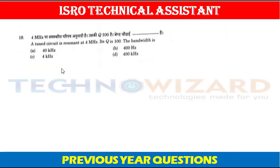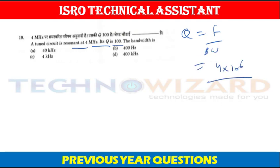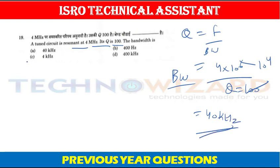Question number 19. A tuned circuit at resonant at 4 MHz, its quality factor is 100. Find the bandwidth. We know that quality factor is defined as the frequency upon bandwidth. Then frequency is given as here 4 MHz, that is 4 into 10 to the power 6 upon bandwidth. The quality factor is given as 100. This 100 will divide by this. This will be 10 to the power 4. Therefore, 40 kHz will be the bandwidth of the tuned circuit. Therefore, option A is the correct answer.